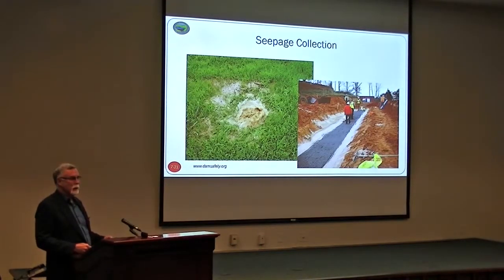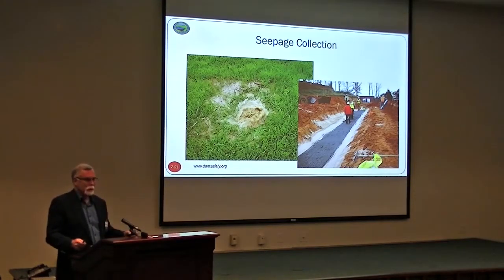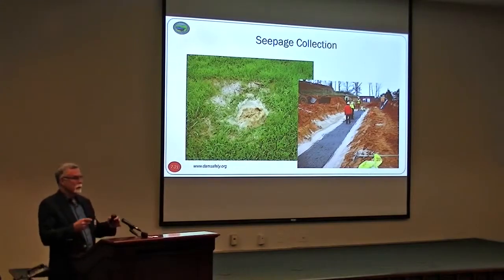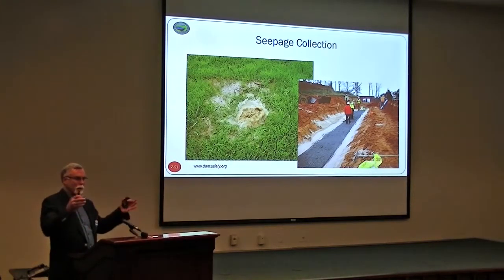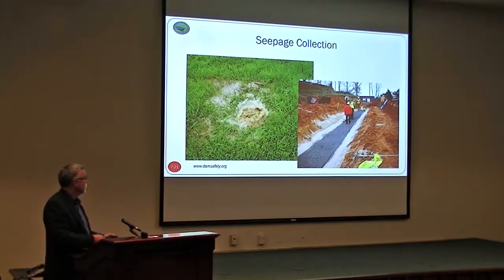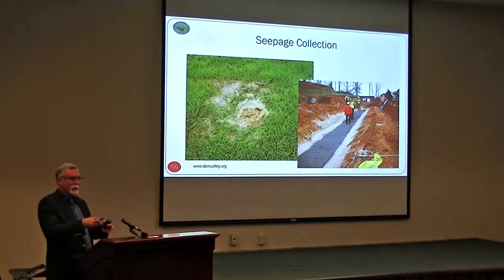So we put in these drains. I showed you a picture earlier. The sand and then the gravel, and then they'll put perforated pipe. Typical construction. Years ago, 20 years ago, we used to use filter fabric. It's a cloth-looking black material. We said, hey, we can dig a trench, line that trench with filter cloth, and then put gravel in there.